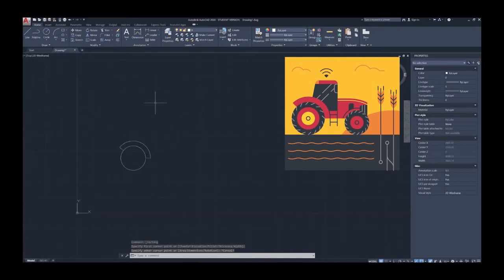Next we're going to add a rectangle to this tractor wheel for the cabin part. So I'm going to choose the rectangle tool, okay? I'm going to click in the open space, okay? At the bottom in my command bar, it's asking to specify other corner points. I could just choose that I want my rectangle to be this big, click and press escape, or I could choose the dimensions, which sounds pretty good. So I'm going to choose dimensions.